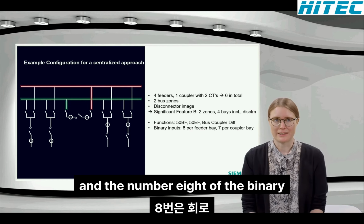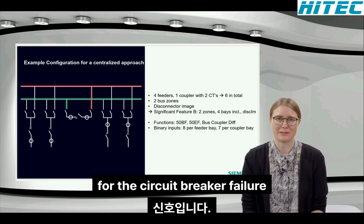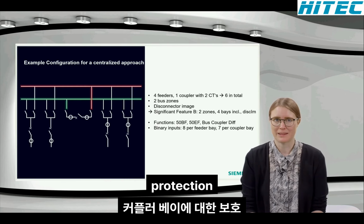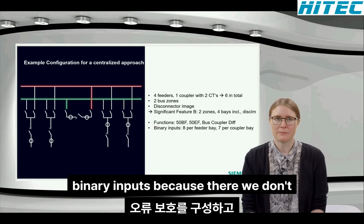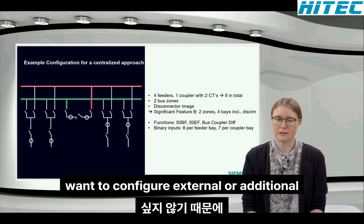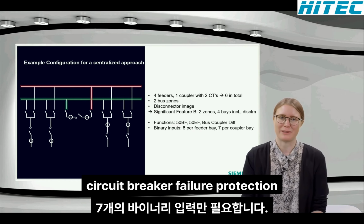And the number 8 of the binary inputs that we need is the start signal for the circuit breaker failure protection. For the coupler bay, we only need 7 binary inputs because there we don't want to configure external, additional circuit breaker failure protection.